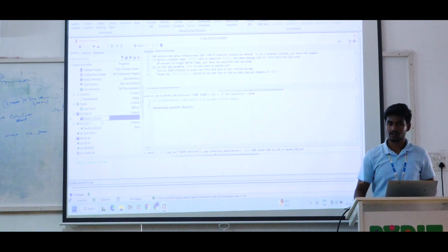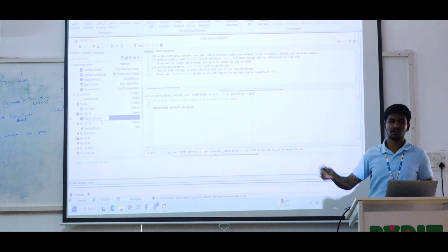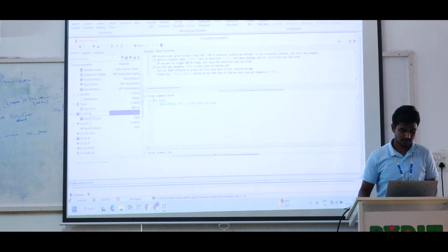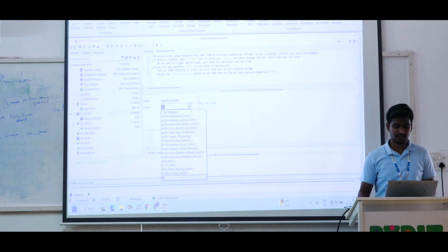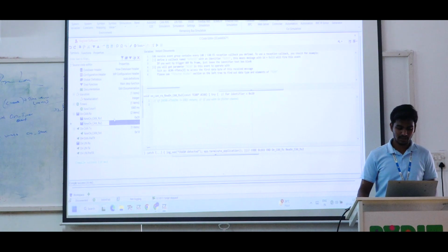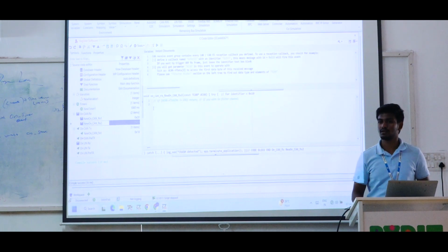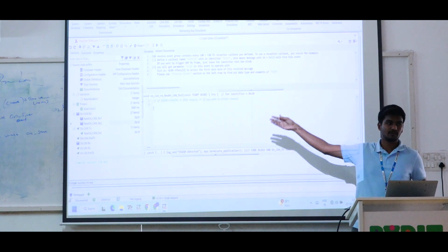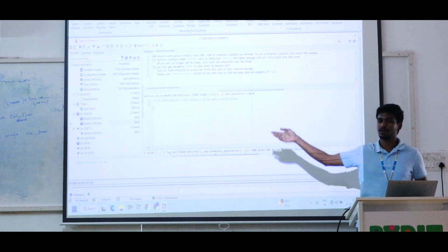And only one RX, right? You have to create more RX, like On CAN RX. Stop the scripting, right click, add CAN RX, and you have to add more messages. For example, add the EMS and then click apply. So in this RX2 you have to write different kinds of code, create different variables, store the values and print them.